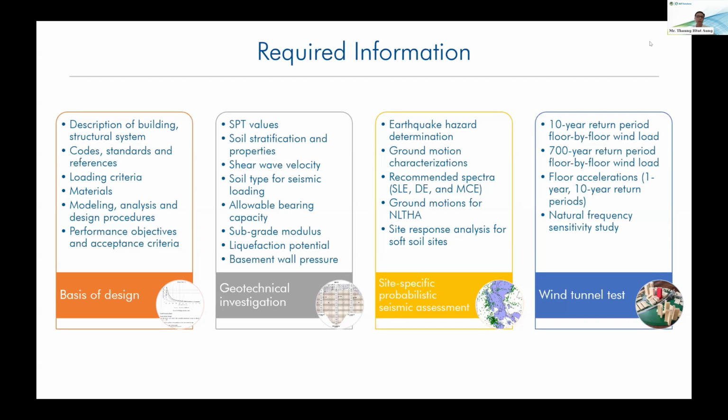And the second one is geotechnical investigation. The geotechnical consultant will provide us the soil bearing capacity and subgrade modulus to use the soil springs in our models. They also check the soil type for the seismic loading. If we have a basement wall, the consultant will provide the basement wall pressure under earthquake. If the site is on soft soil and there is a liquefaction potential, they will check the liquefaction effect in the soil and also provide the lateral subgrade modulus for the piles, which is reduced due to the liquefaction effect. And the third one is the site-specific seismic hazard assessment.